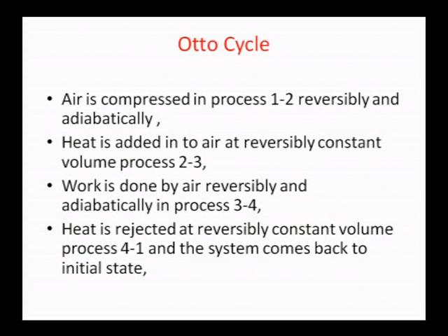So, air is compressed in process 1-2 reversibly and adiabatically. That is, 1-2 is compression. Heat is added to the air in a reversible constant volume process 2-3. In 2-3, Q1 is the heat added or heat supplied into the system.